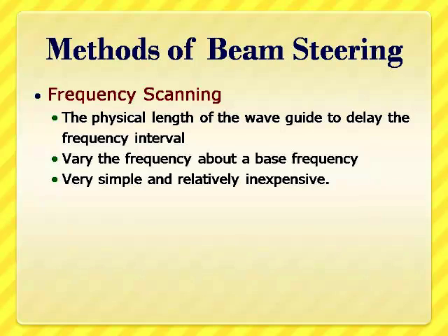Frequency scanning. The physical length of the waveguide is used to delay the frequency interval to get this phase shift, and another one is to vary the frequency about a base frequency value. And the advantage we are going to have is it's very simple and relatively inexpensive.